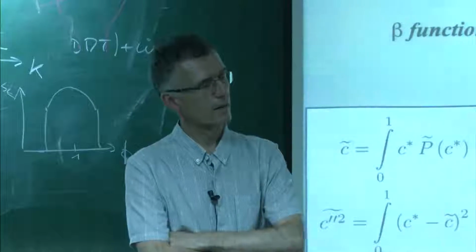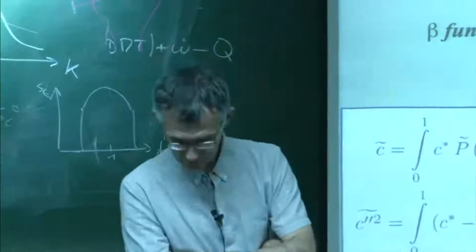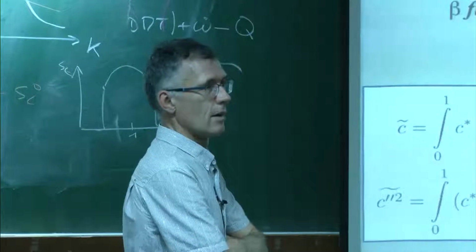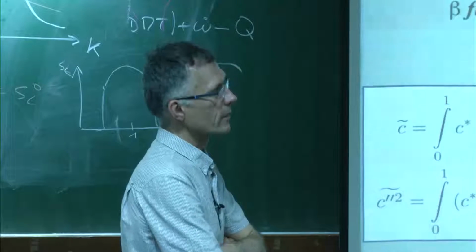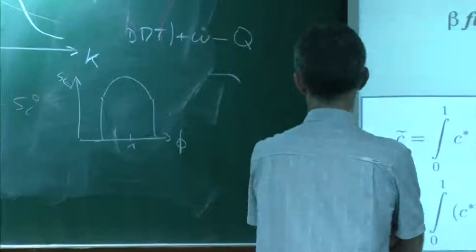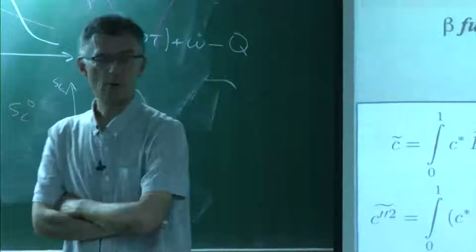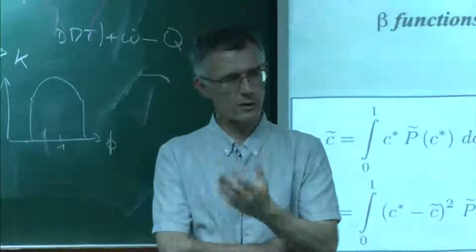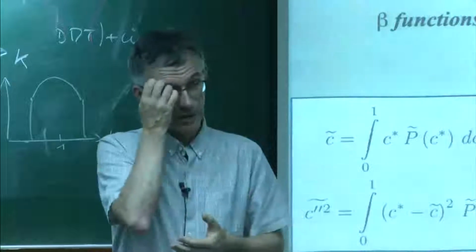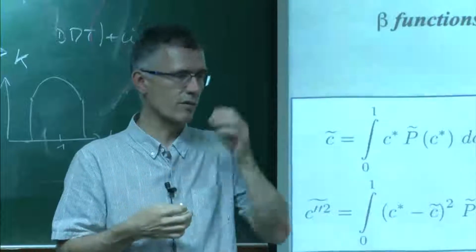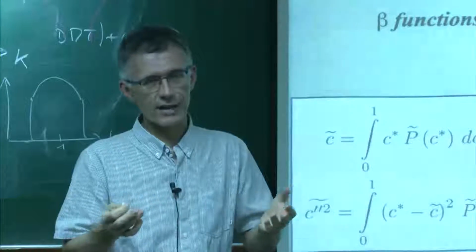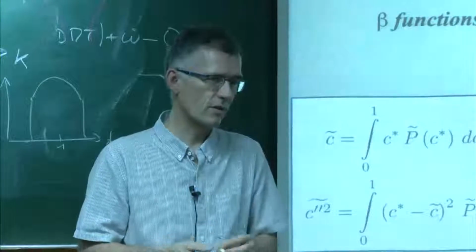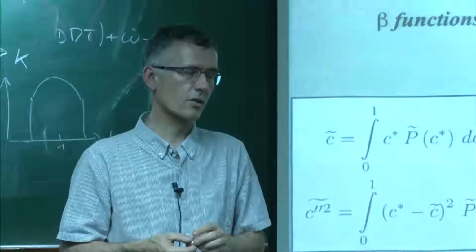In case of effects like blow off and quenching, how accurately can we predict with RANS? Well, quenching. If you're using the eddy breakup model, it will never quench. Which means that if you want to have quenching, you have to introduce it somehow. The way you do that depends on what you believe is important. You can have things like, if the equivalence ratio is too low, you bring the constant to 0. But after that, it's all going to be a model, okay?